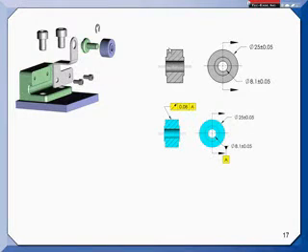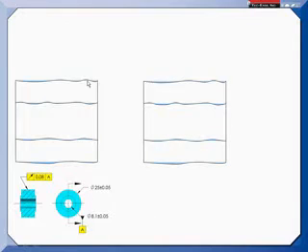And I'm worried about the surface of the roller, certainly, and I'll have something like a runout going back to that axis established by datum feature A. You talk to the supplier, and the supplier often will want to turn this around. He'll say, don't you know anything about making parts? I want to grab this on the outside diameter, and then I'm going to machine that hole in there, that bore. So I started with this drawing, and let's see what this means.